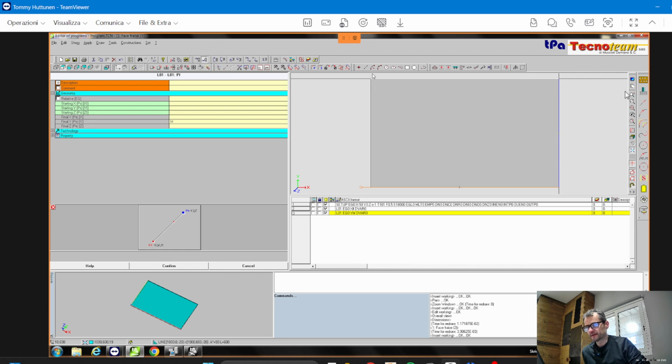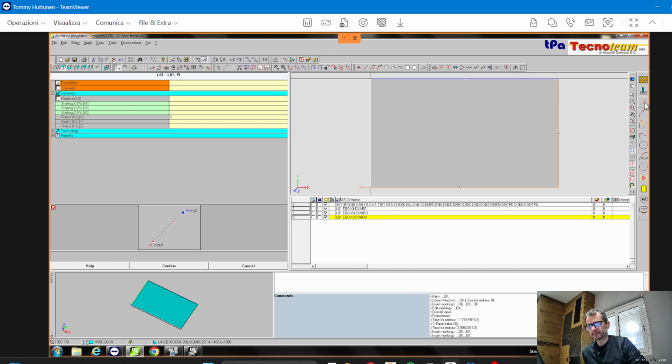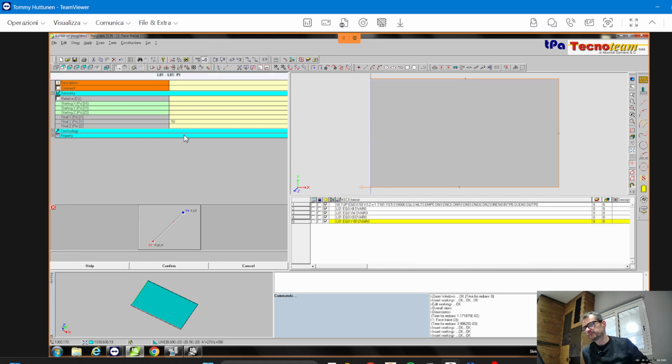So now I just have to come here. Another line. Okay, the x-axis is the one that moves because the y-axis stays in the same position. What is the number that you have to write for the x here? Do you know what this position is? 0. Yes. And then the last movement, another line. I need to move the y-axis, and I will go to 0 again. This is 0, so it can be 0, it's okay. I just put something with the minus because I want to pass a little bit over the point. So it's completely clean and well done.